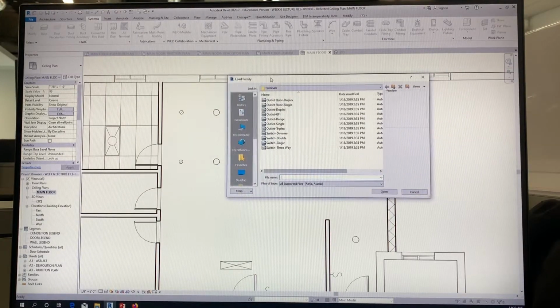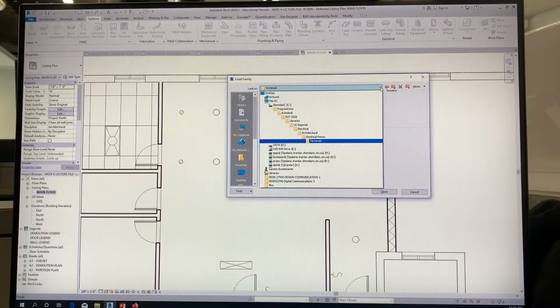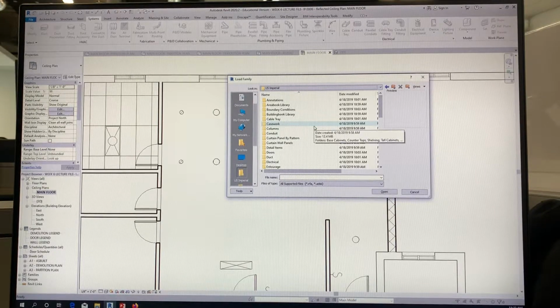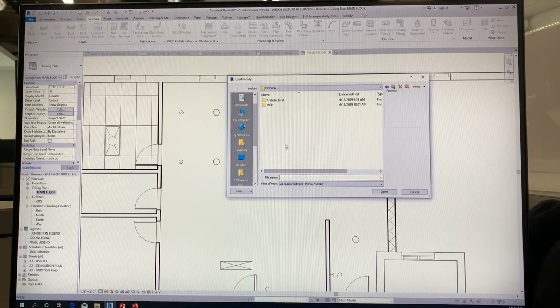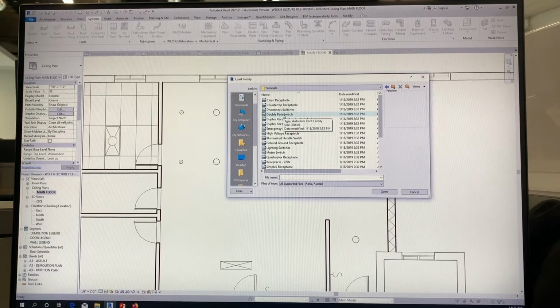And here's where you have to go for this. So let's take a step back. We'll start back at the US Imperial. It's still under Electrical, so click on Electrical. But this time, instead of going into Architectural, we're going to go into MEP, Mechanical, Electrical, Plumbing. Then go under Electrical Power, and then go under Terminals. In here, you should see lighting switches. So right here, lighting switches.